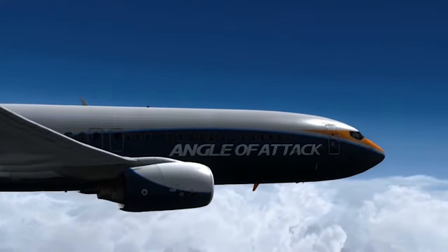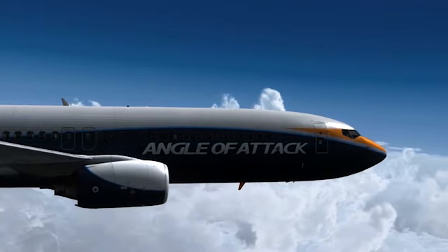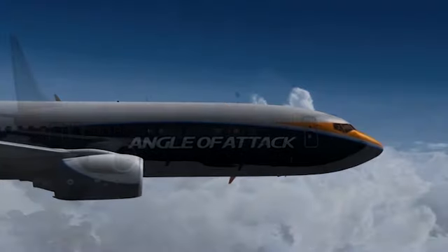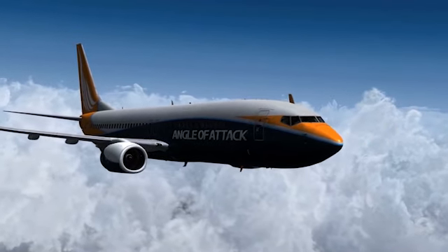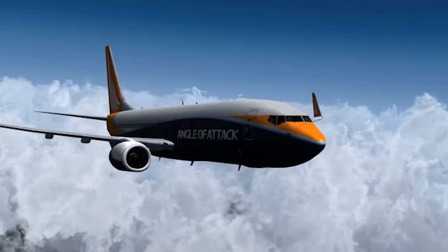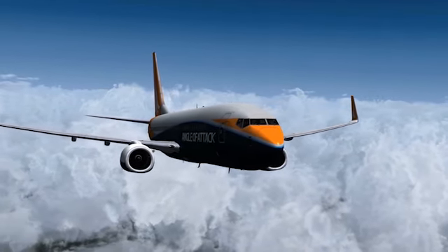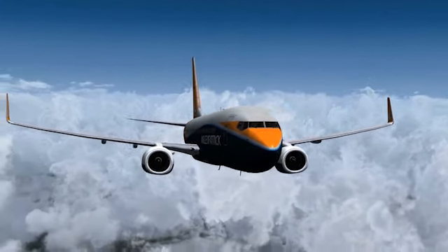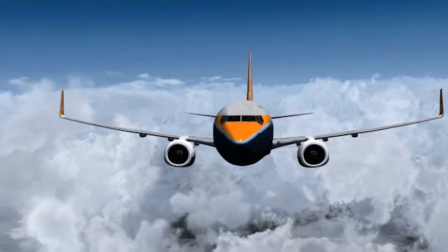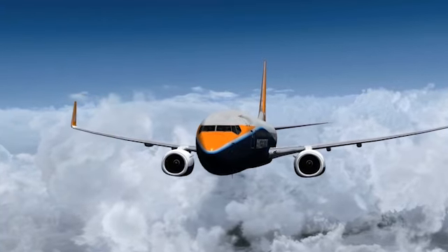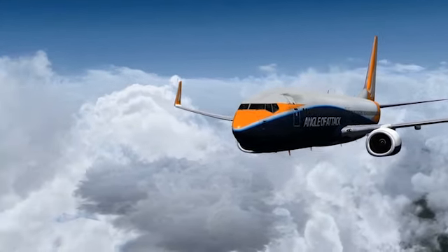We've mentioned many items and components associated to the electrical system on the 737NG. What would happen if all primary sources of energy were to fail? Requirements for aircraft certification demand that the aircraft should have alternate and backup sources of power, which need not be unlimited, but should at least keep the aircraft electrically powered for a known period of time. In the 737NG, this system is known as the standby power system.